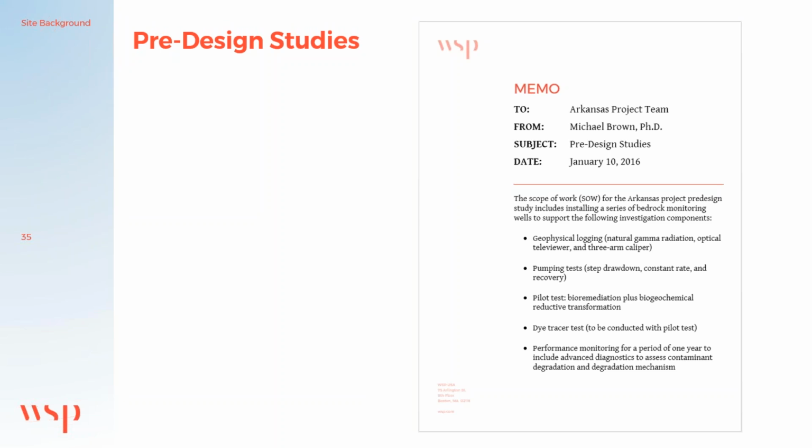We're actually in the middle of it right now. The pre-design study includes installing wells for a pump and treat pilot test or pump test, and for use as injection points for an in situ remediation pilot test. It also included collecting data about the nature of the sandstone fractures, fracture faces, and a pump test to determine hydraulic characteristics of the fractured sandstone aquifer. I'm not going to get into the pump test results. That's information for another webinar.